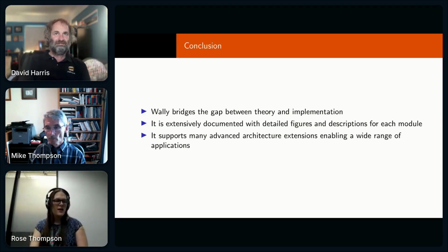This was a bug on the ECU 118 board. The UART to USB chip on that board is not programmed correctly, and it's configured in a loopback mode, but I didn't know that when I was setting up the board.